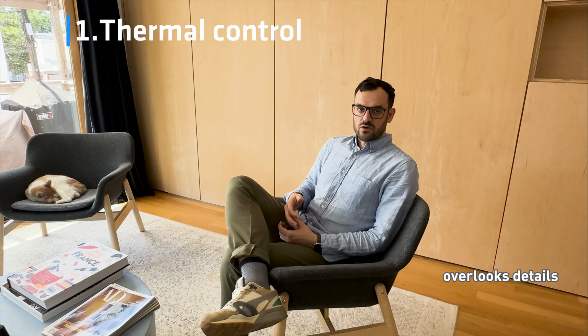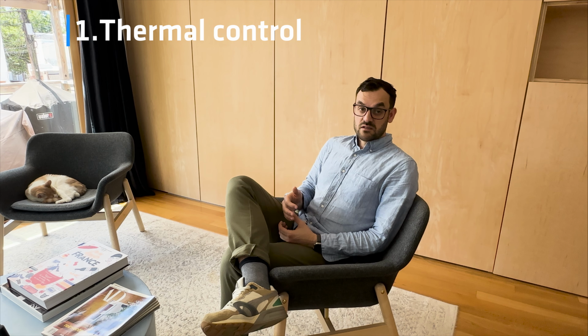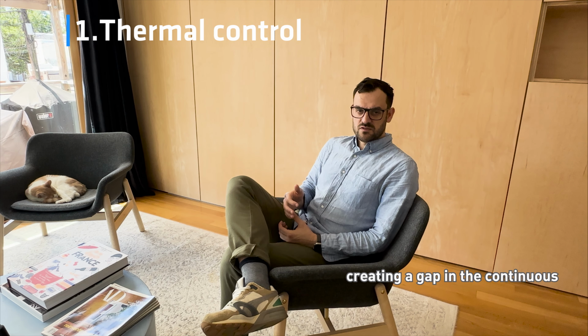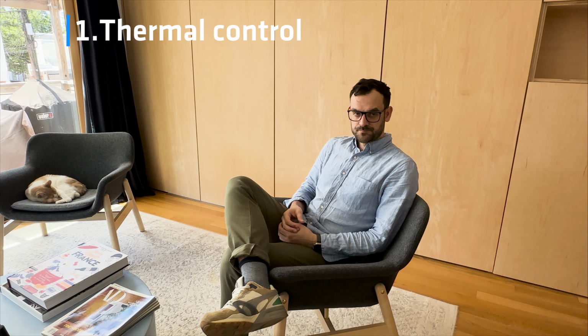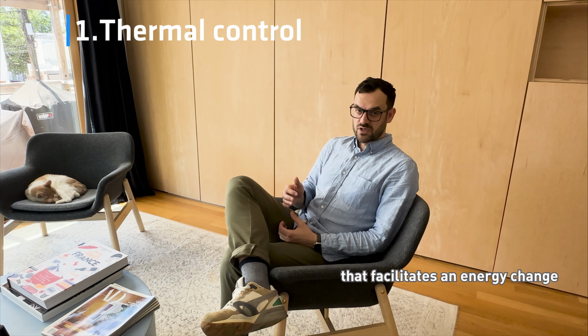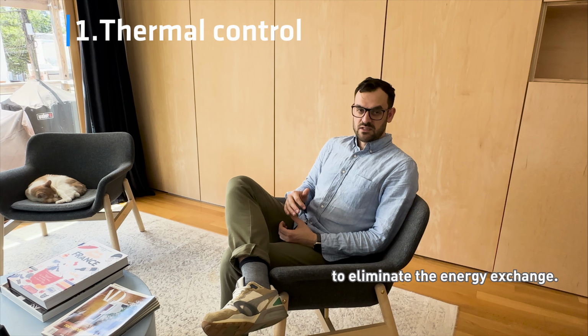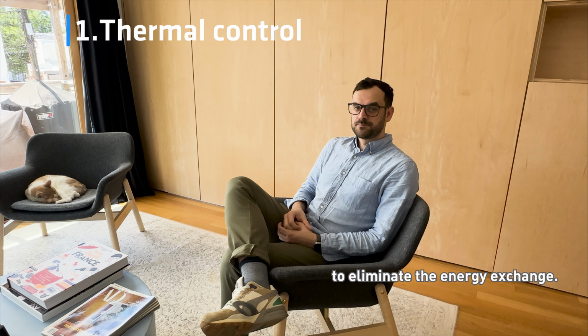Conventional construction overlooks details where material is both inside and outside, or insulated elements are misaligned, creating a gap in the continuous insulation layer. This results in a thermal bridge that facilitates an energy exchange. With passive house design, all those details are studied and addressed to eliminate the energy exchange.